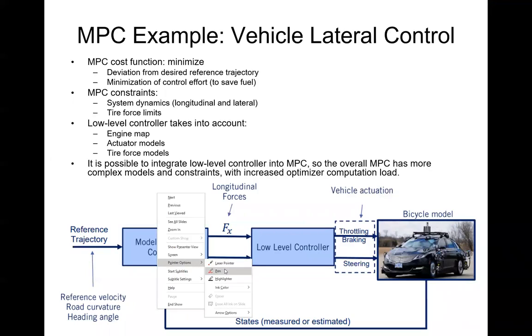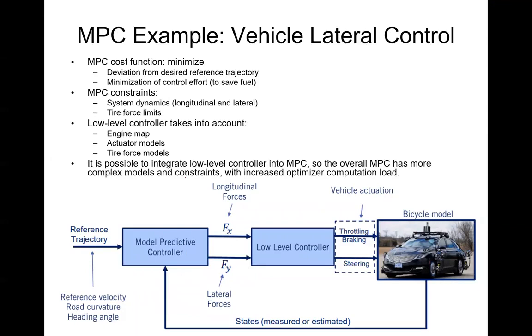In the automotive industry, they often use a map to generate control inputs to the car. Essentially, the control law is expressed as a lookup table, a map, given as input the required forces, and then you do a lookup to get the resulting actuation commands.